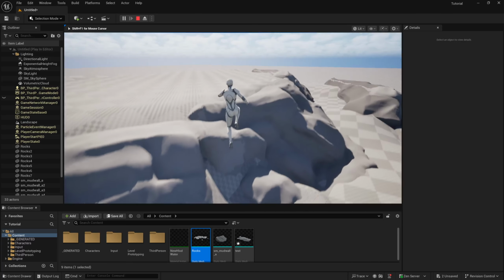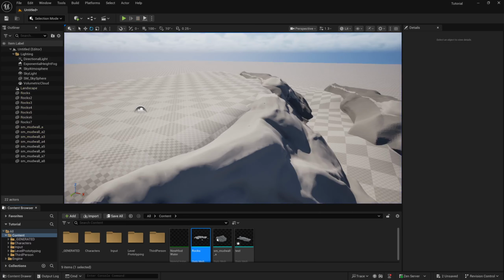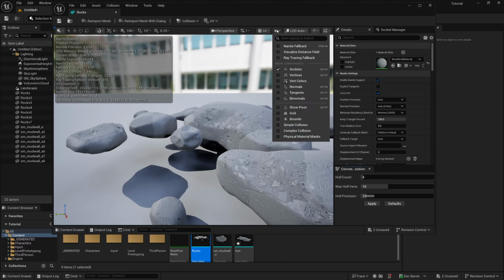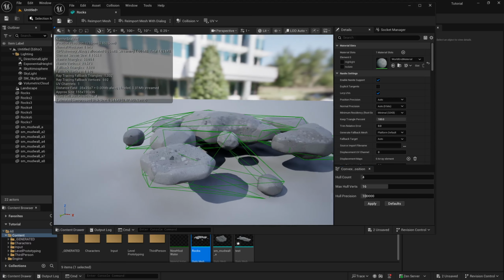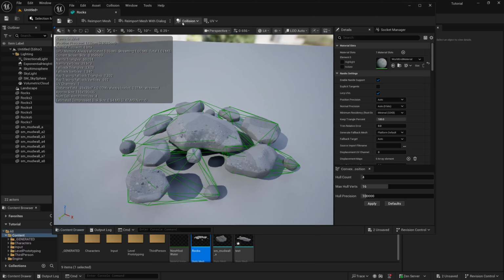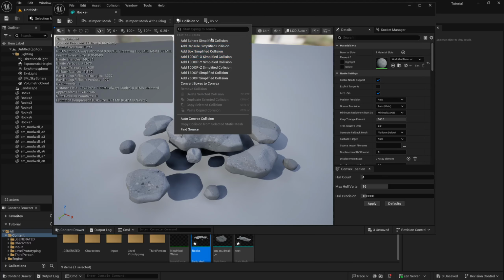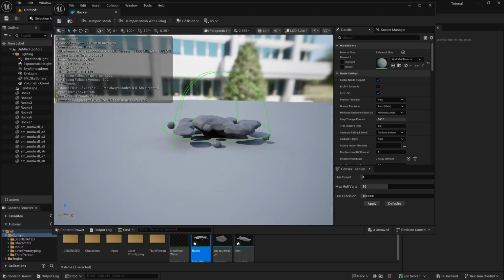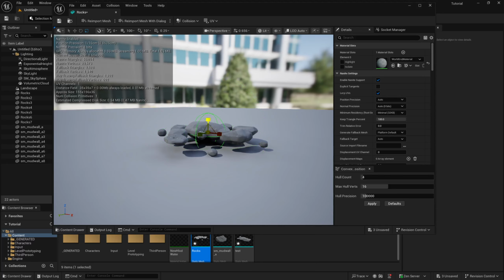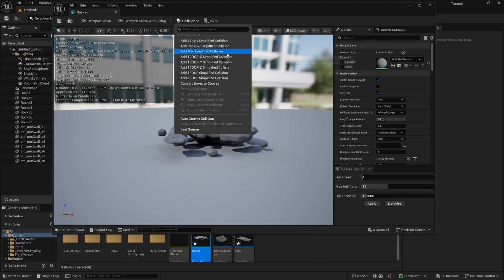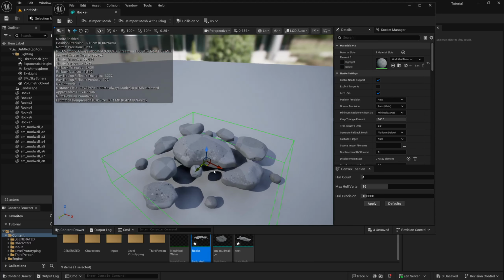It's right there, by the way. You didn't know that. Here, I'll show you. We know we're going to do our collisions. We already have collisions, but we don't like these collisions. We can remove collisions. We can add collision boxes or spheres or whatever. So we can do that number. See? So now we can move and rotate and scale them a little, maybe if we needed to. But there's all kinds of ways of doing stuff. Like you can hit delete, do a box one. Fortunately, it's usually boxes and spheres. And so for something a little bit more custom, you'd probably be in Blender for it.